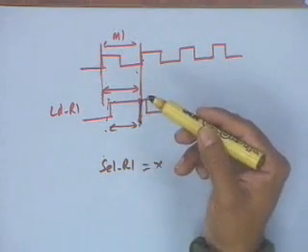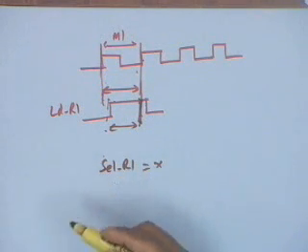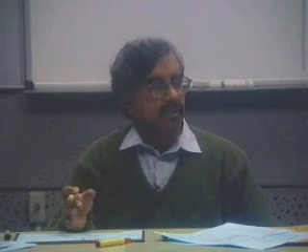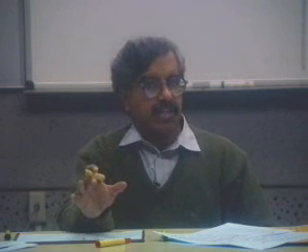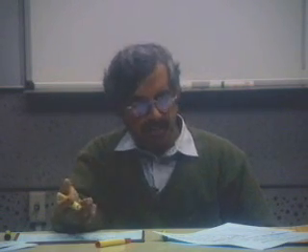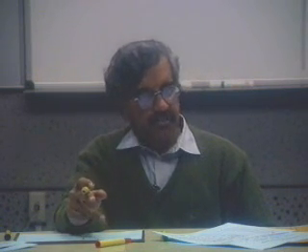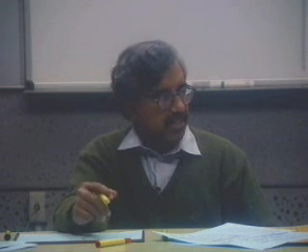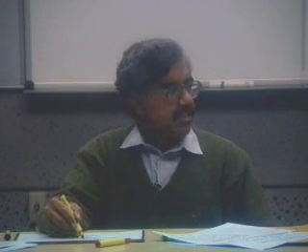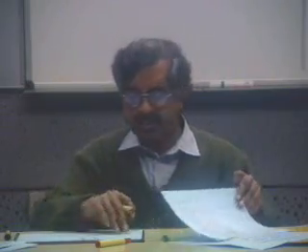Similarly, when you are doing subtraction, you select the inputs to the subtractor through multiplexers and perform the subtraction. There is no control signal for performing the subtraction. The subtractor unit performs only one operation, so it doesn't require any control signal. It directly performs the subtraction. Its output goes to the input of the multiplexer for R1, flows through the multiplexer, and becomes available at the end of the clock period. So the model is that the operation completes at the end of the microinstruction.